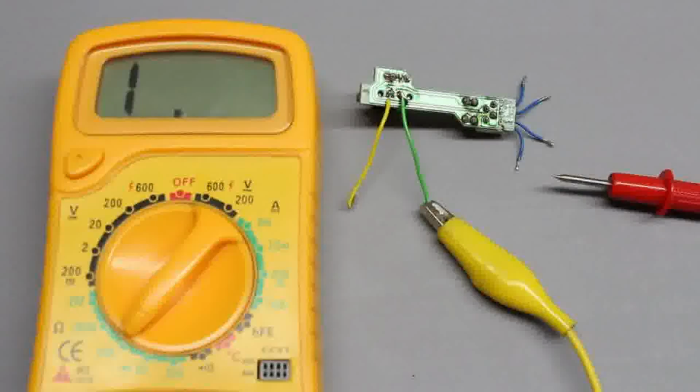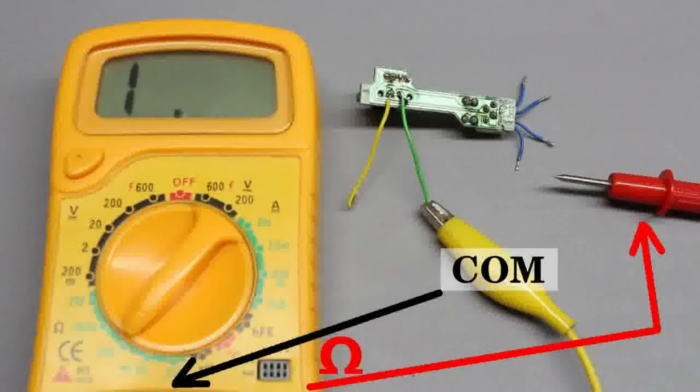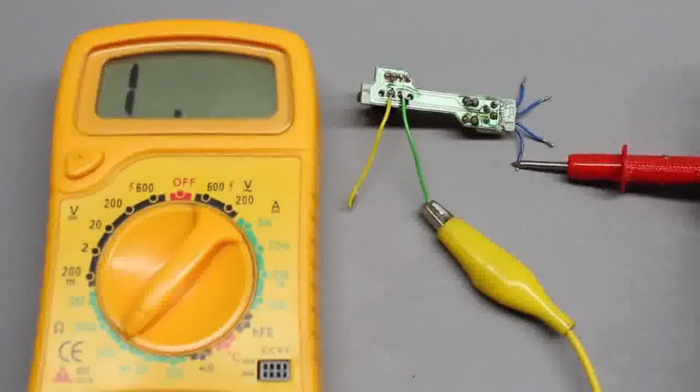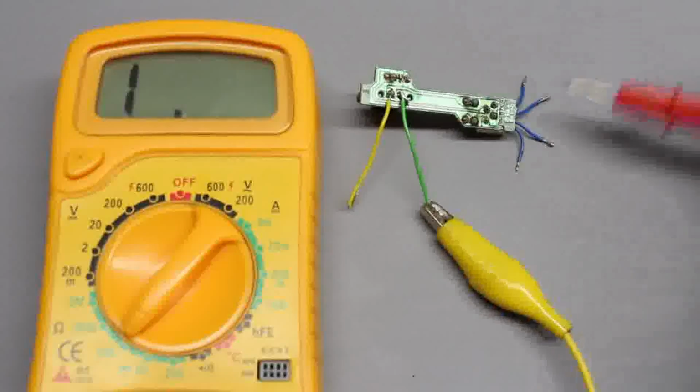If there is no clear view on the tracks of the board, you can record the resistance between LED pins and plug. Connect the common terminal of your multimeter with the pins of the LED during measurements. The red probe runs to the ohm input. The lowest values recorded are the tracks running to the cathode and the anode of the LED.